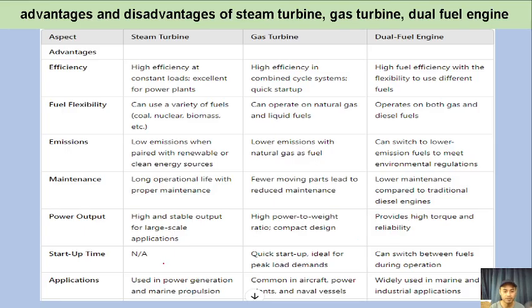Startup time, not applicable for steam turbine. Gas turbines, quick startup, ideal for peak load demands. And dual fuel engine can switch between fuels during operation. So for steam turbine, we usually heat up the water first to create steam, so startup time is a little bit time consuming. Okay, for applications, steam turbine is used in power generation and marine propulsion, gas turbine is common in aircraft, power plants and naval vessels, and dual fuel engine is widely used in marine and industrial applications.